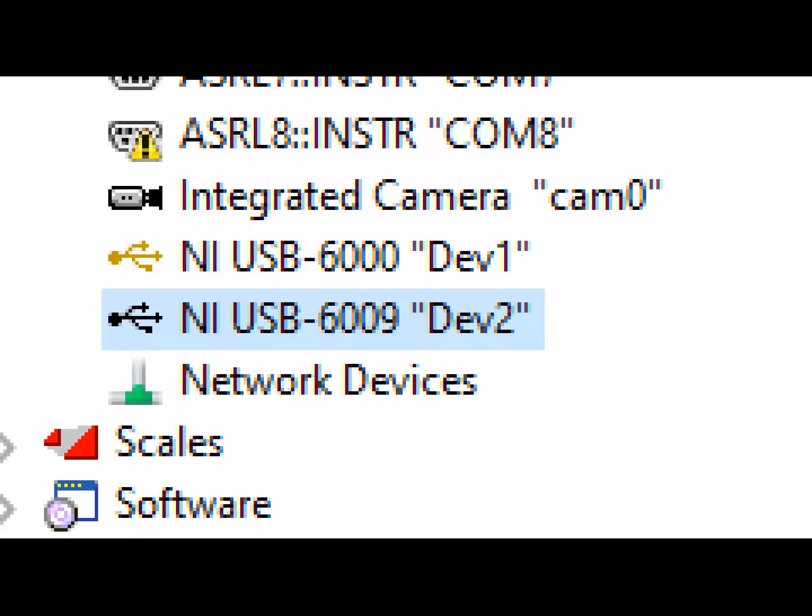Okay, what's the difference? Look at the color of the USB icon or the symbol. Oh, I thought that's just because of selection. Yes, correct. Black, and that one is gold or orange, some people say orange. It doesn't matter. But you want to note that when your hardware is plugged in, it is black color. You know the USB symbol, right? When it's black color, it means that your device is physically connected. It is physical. You have a real device there.